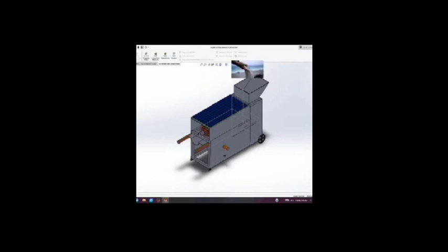The homogeneous mixture of sand and pebbles is fed from a slider which falls on the sieve net fixed on the rotating shaft. Then, due to relative motion between particles and the rotating sieve, the smaller particles pass through the net and the remaining particles fall on the other side. The fine sand will not directly fall onto the ground. It will be stored in a hopper for the automatic filling.